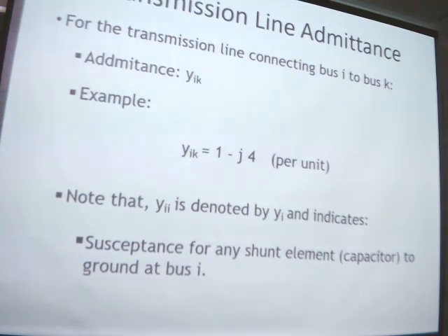We can reverse to admittance, because YAB we can easily understand as the admittance from bus A to bus B. But for YAA, with the other buses grounded, you can calculate the admittance from A to the ground. No problems here. This is per unit.